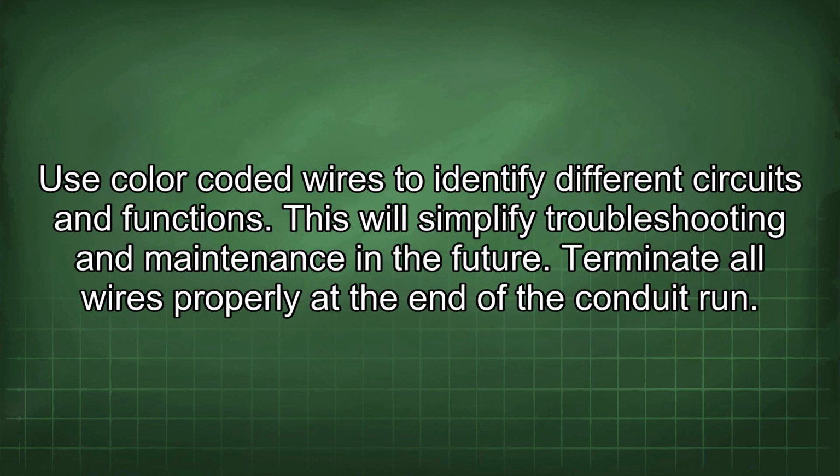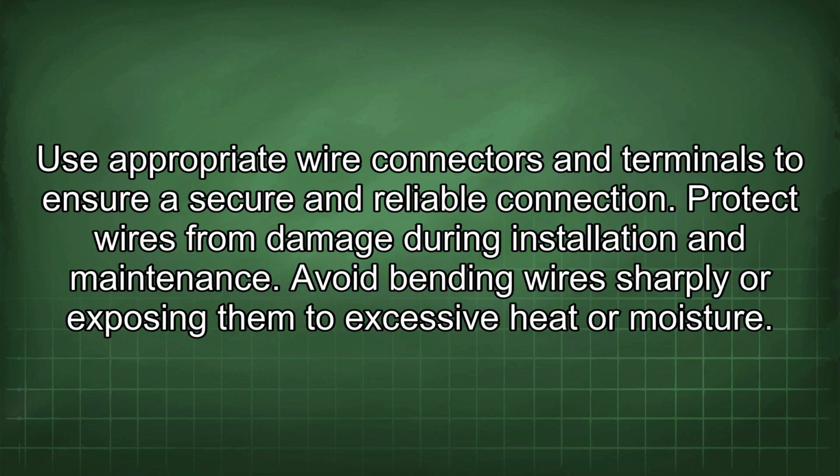Use color-coded wires to identify different circuits and functions. This will simplify troubleshooting and maintenance in the future. Terminate all wires properly at the end of the conduit run. Use appropriate wire connectors in terminals to ensure a secure and reliable connection.